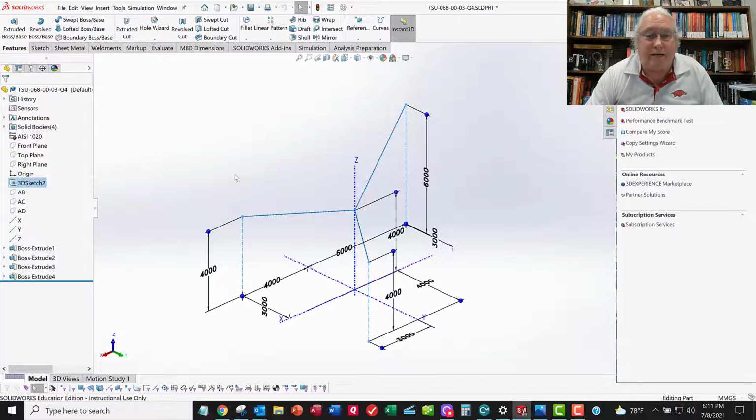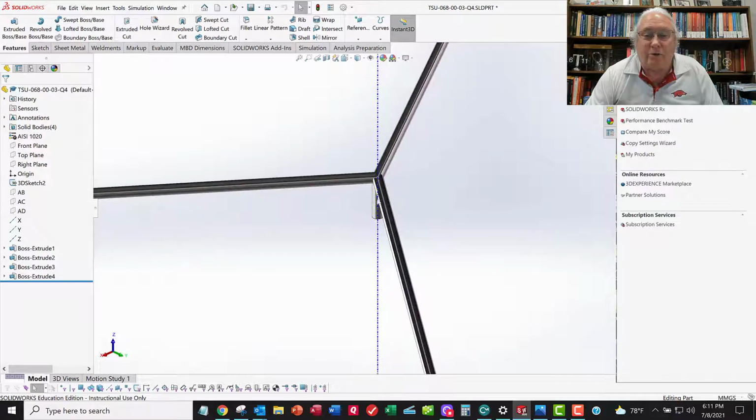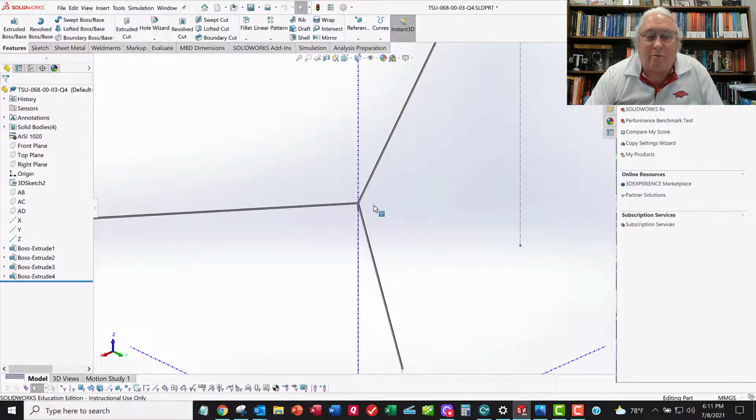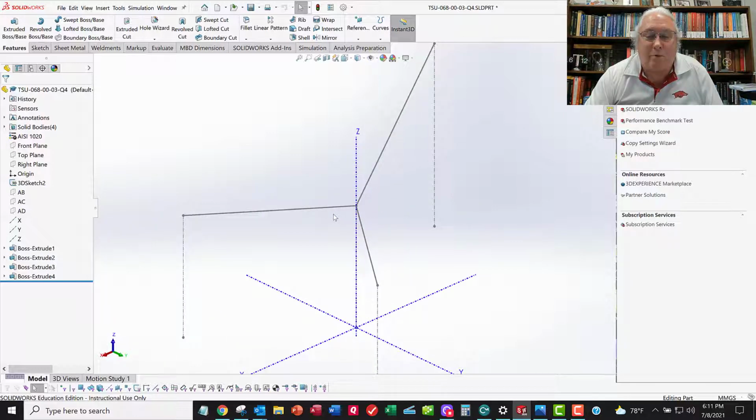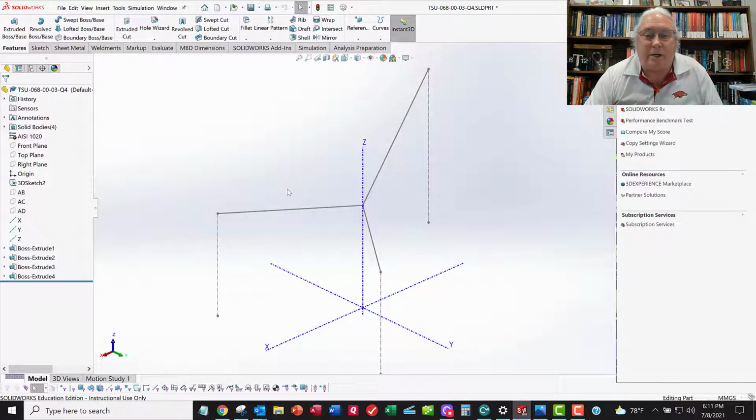And then I just created some boss extrudes, just some circles here. This is some steel tube. It's going to represent these cables that I'm assuming are pretty much no deflection, and you can't pull on them and extend them. So it's not like a rubber band, it's like a cable, steel cable. So we should have near zero deflections. And we'll check the displacements to make sure that's correct.